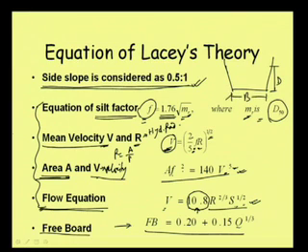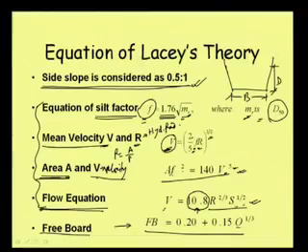So, we have got this design, but when we are putting the channel in the field, we cannot make it exactly equal to D, because due to many reasons this depth can increase beyond that, or maybe waves are coming through this channel, and that way also it can exceed this limit. So, always it is necessary to provide a freeboard.